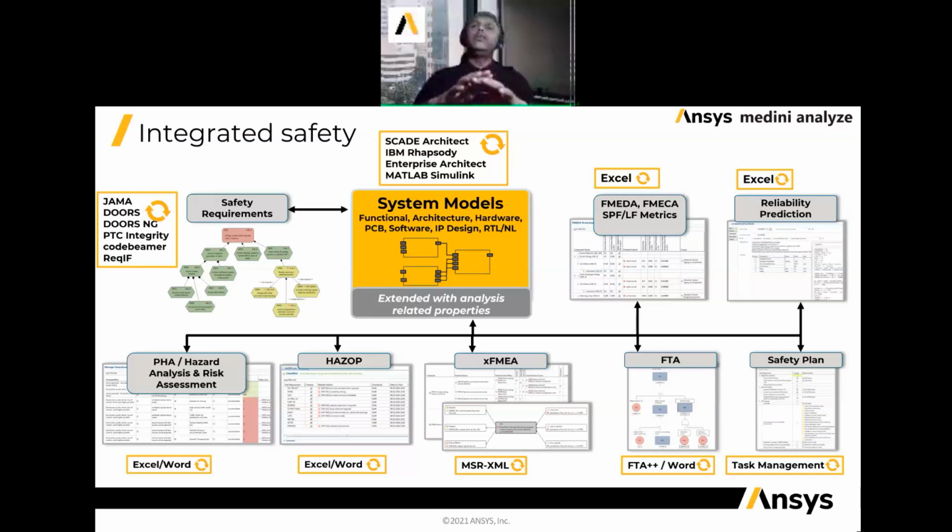And then finally, we will be able to add up all of these failure rates together at the module level. You can understand what is the failure rate of your overall application or overall hardware. And then we can perform your diagnostic metrics, diagnostic coverage analysis, where you can understand whether a particular failure really contributes to the violation of your safety goal. And if it does, then do you have any mechanisms to detect such failures? Or do you have any mechanisms to prevent such failures? And what confidence do you have in the mechanism you have put together? And finally, what is the residual failure?